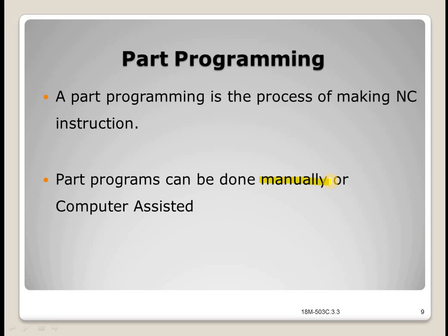Manuscripts come in various forms depending on the machine tool and tape format to be used. For example, the manuscript form for a 2-axis point-to-point drilling machine would be different than one for a 3-axis contouring machine. As mentioned, the manuscript is a listing of the relative tool and workpiece locations.